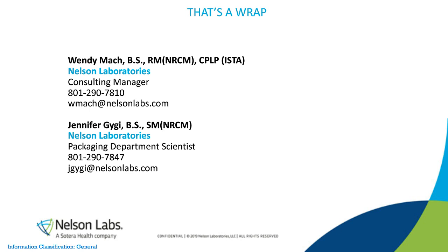The burst testing is a whole package test, and the whole package would be inflated, and then we would get a burst pressure. The seal peel testing is a coupon test, so 1 inch of the seal is tested. They're both acceptable methods. The burst test does not correlate to seal peel testing because the burst test is dependent on package size and materials, and the seal test would be a much more uniform test because since you're cutting a 1 inch coupon, now you can compare that 1 inch coupon from a small pouch to a large pouch and get an effective comparison.